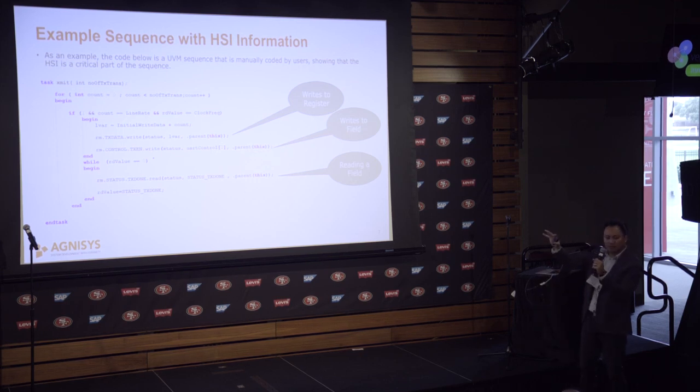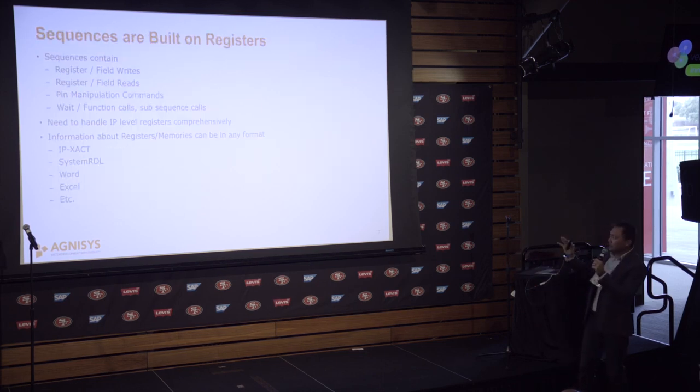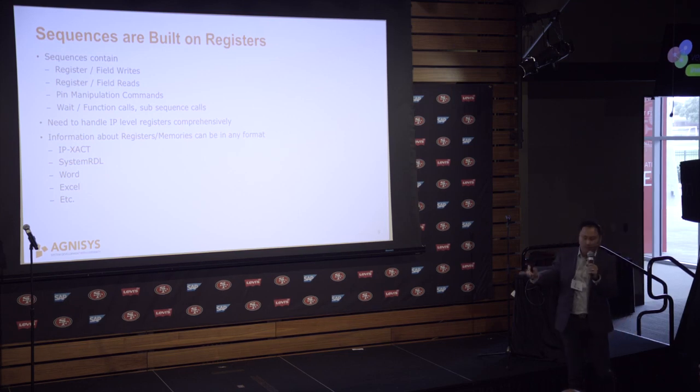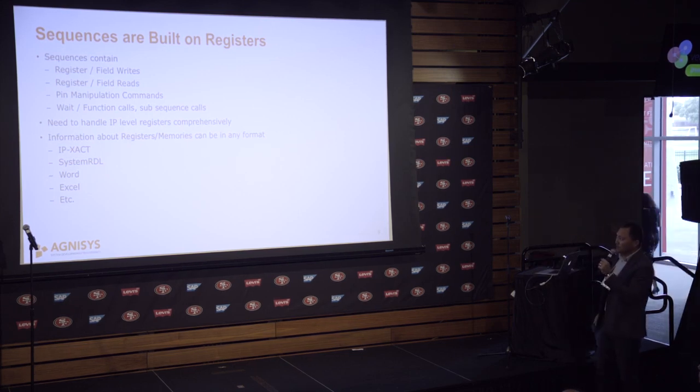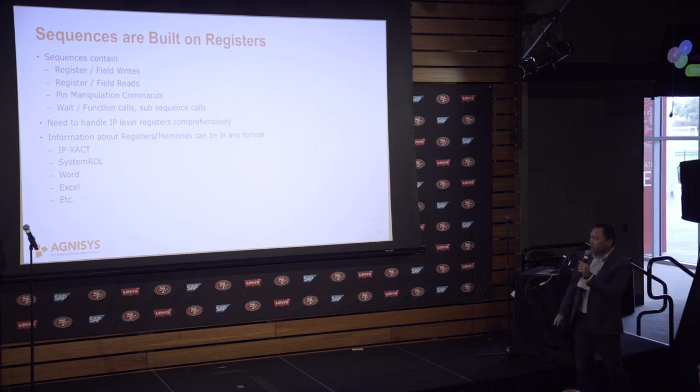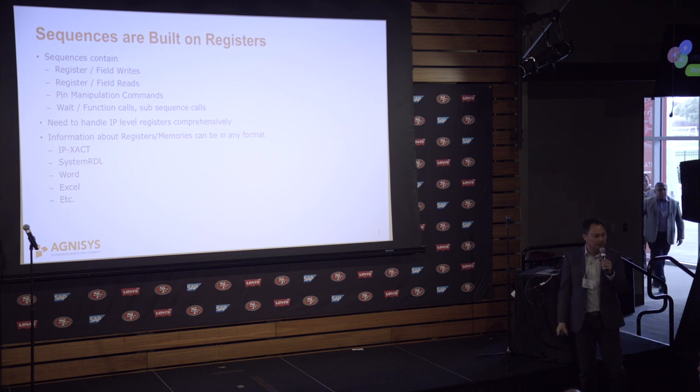So the reads and writes to the registers are critical to the sequence, and so sequences are built on registers, as you see. The sequences can contain register field writes, reads, pin manipulation commands, wait function calls, and subsequence calls. Registers, as I mentioned earlier, exist in so many different formats. That's very true for any SoC company, because there are a lot of sub-IP teams who maintain registers in IP-XACT, SystemRDL, and the ability to parse all of those files and put them together at the SoC level is not that easy.